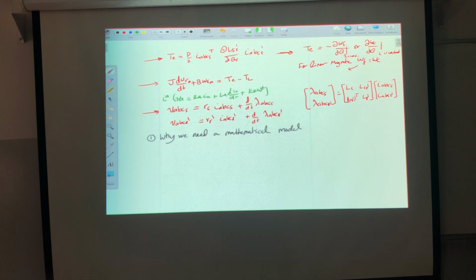Except that the induction machine is difficult. Three-phase, polyphase. It's time varying. Why time varying? The inductance matrix depends on theta. Do you remember which one? L_SR, L_SR dash, let's say, was a function of theta_r.